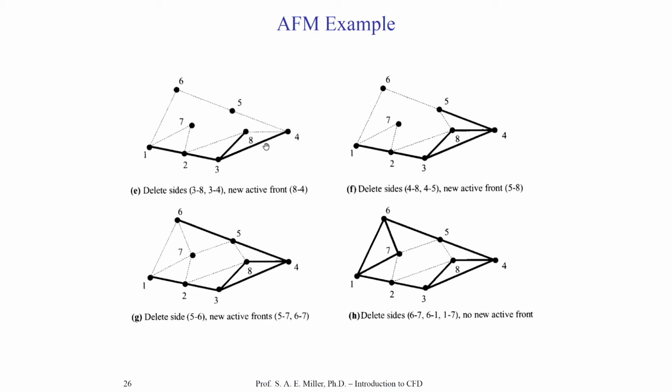And of course, we remove the advancing front from 3 to 4, and now we can create another new connectivity as in part F. We don't need to necessarily just keep creating connectivity as we go around the advancing front. We can just either keep adding nodes or create new connectivity. There'll be logical algorithms in the computer code using if statements or checks or geometry or all kinds of other types of things which are the object of research so that the advancing fronts do not overlap.